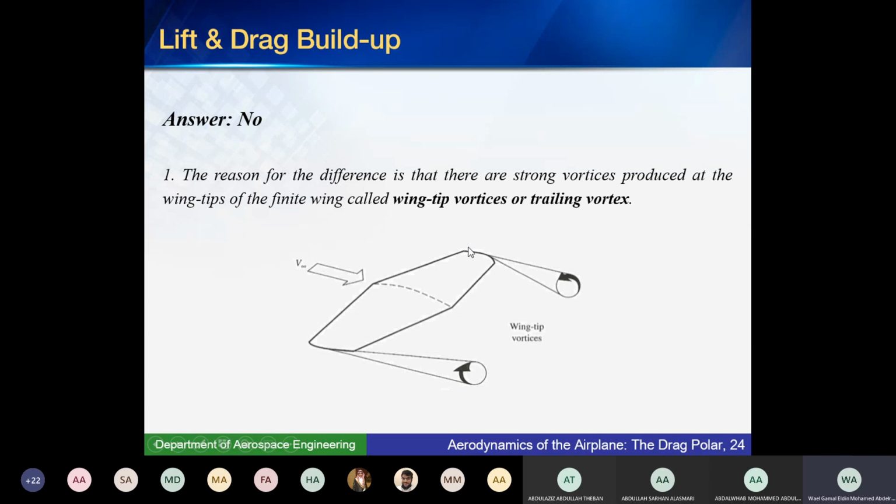But whatever goes up will go down again. And then it will move up, down as the wing moves through the air. So as the air continues to move up and down, it will start to circulate and move away from the wing in what we call the wing tip vortex. This wing tip vortex has some desirable and some undesirable effects on the aerodynamics. In a sense, it will reduce the angle of attack because it will go down.